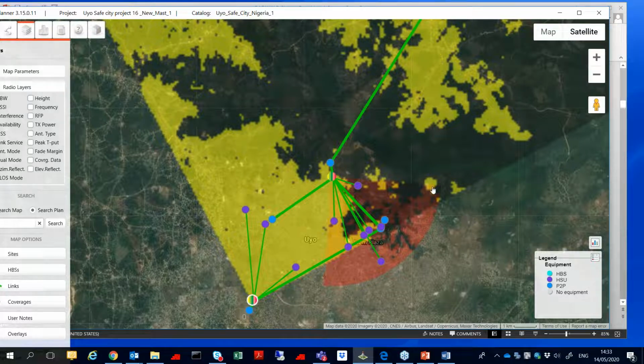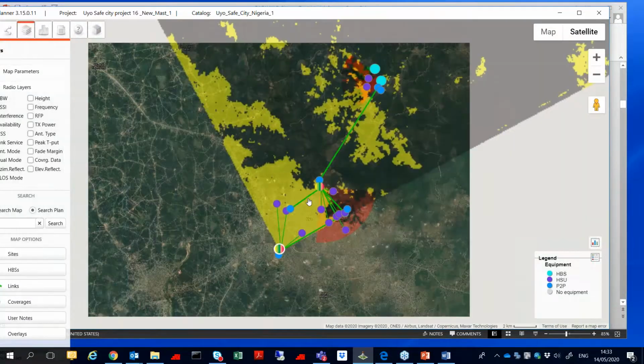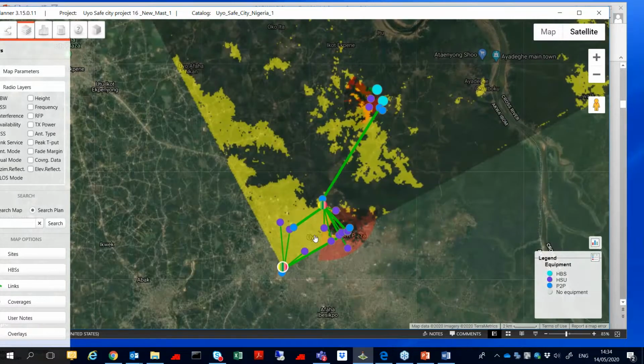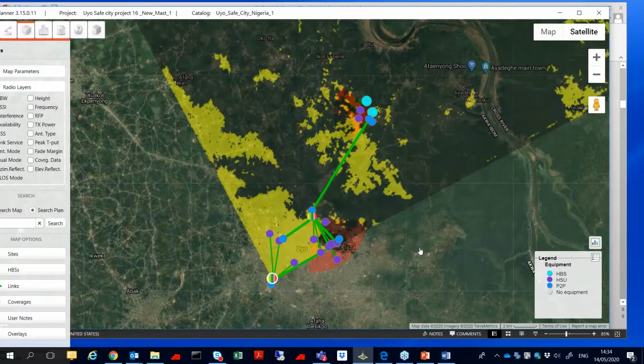But of course, when you are taking a 16 dBi antenna to 5 kilometers, it's possible, but you are losing CIR and you are losing resources from your sector. And the sector becomes not efficient.